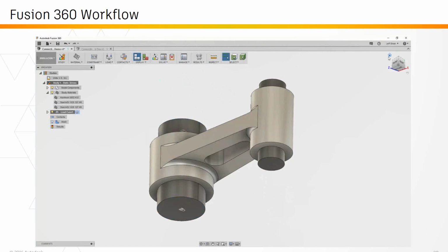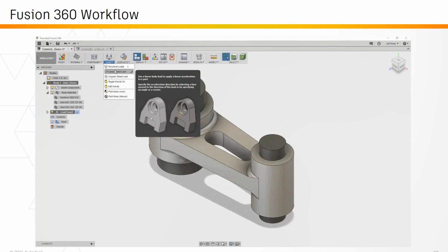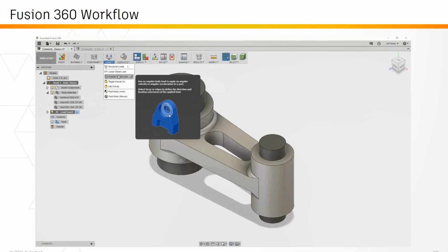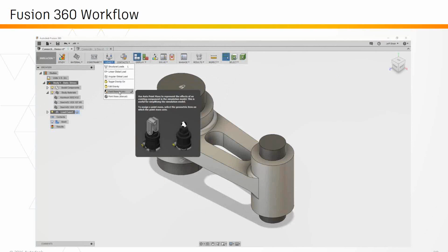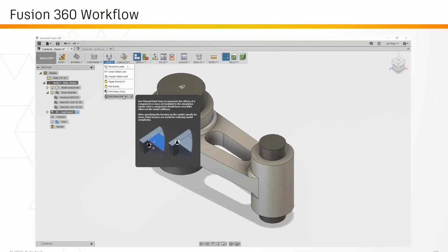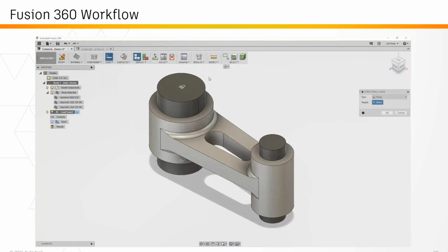And then again, we're moving essentially from left to right across the toolbar, kind of our standard. And again, a number of loads. There's the applied loads, but you also have acceleration loads, including gravity loads. And a nice little feature is that you have this point mass. So maybe you have this really complex motor that's hanging off your structure, and you're only interested in the effect of that mass of that motor on your structure. You can automatically replace that motor, that complex assembly, with an equivalent mass to distribute the load better.